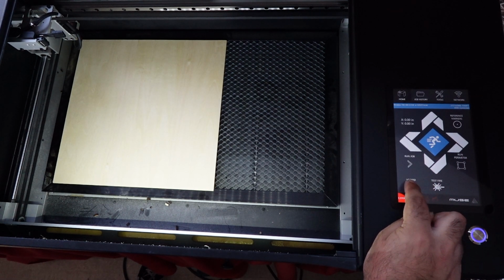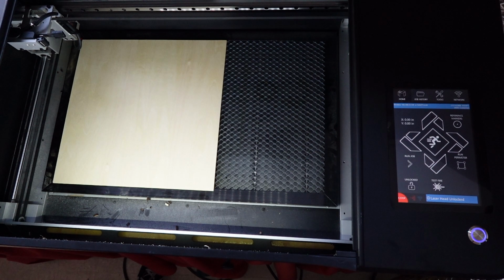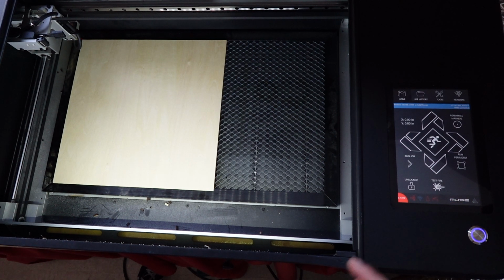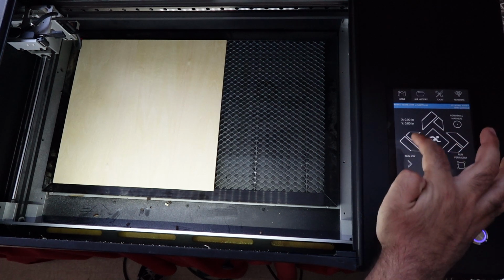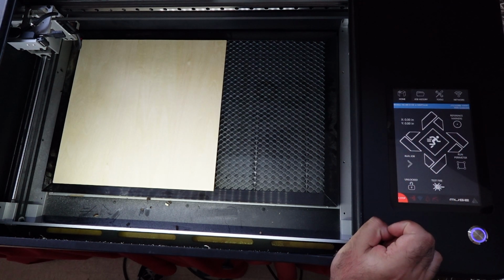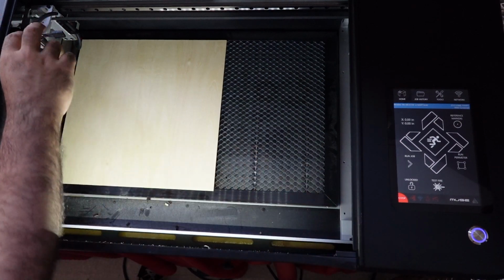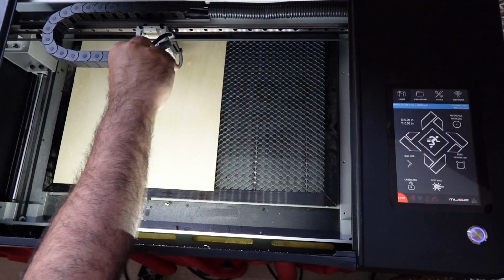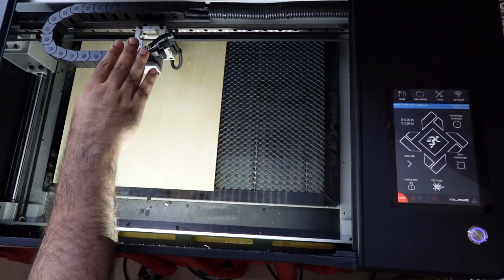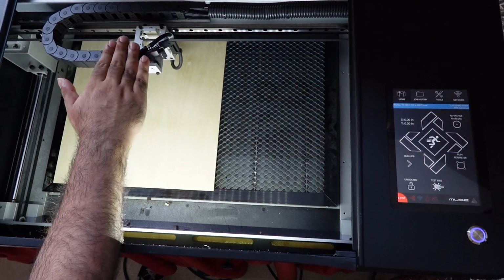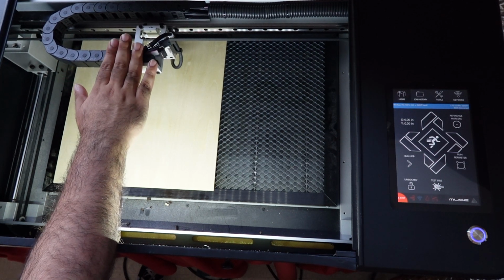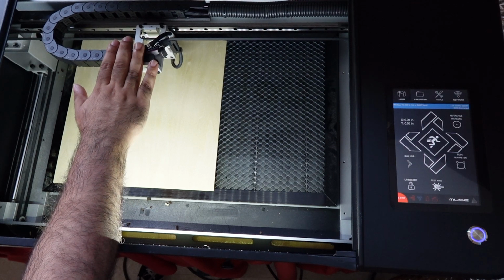When I press it, it unlocks my laser carriage. And I know it's unlocked because I get a blue alert saying laser head unlocked, and also all of my gantry control buttons have gone from blue to clear. Now, I can move my laser head freely, with no resistance whatsoever. Again, you should not move the laser with your hand if you are experiencing resistance. It can damage the motors. You should always make sure the laser head is unlocked before you do so.